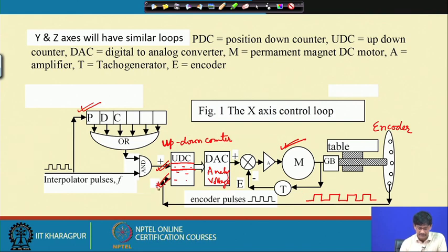By the help of this, we can move along straight lines, we can move along circles, we can move along different types of freeform curves, etc., to cut whatever surface that we want by computer control. So, interpolator pulses will be having the pattern corresponding to which the motor will be moving. Just now what we discussed about constant rates coming in and going out was for cutting of straight line cuts. At that time the motor is supposed to move at a constant speed.